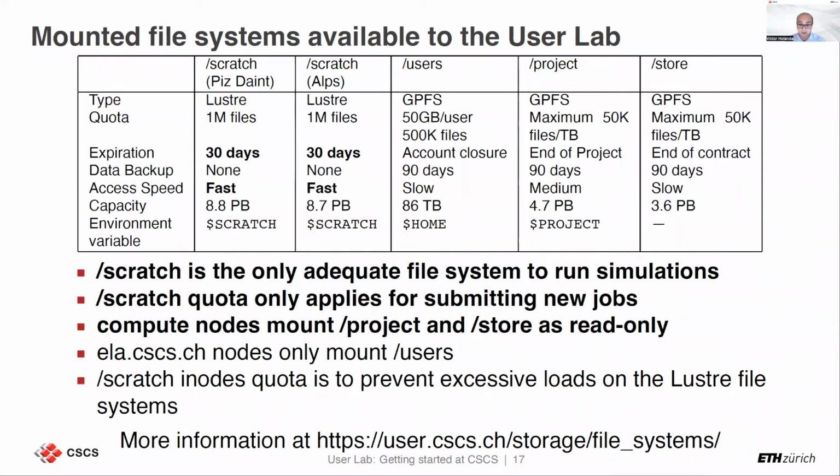account or folder there. There are some things that have to be said here. Scratch is the only one that is mounted fast, with a fast access speed on our side. So it means that it's the only adequate file system to run simulations. Please do not run simulations from home, and you cannot run simulations from project and store because they are read-only. So if you're trying to initiate, for instance, your simulations and write the data directly to project, you can't because they are read-only, right? Because they are very slow in performance. So please use Scratch when running your simulations.